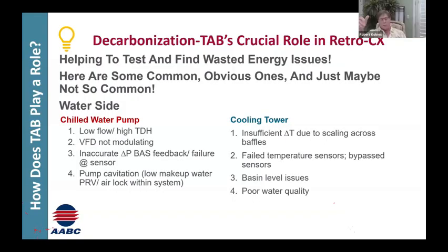I'm also on a project right now where we've got the pumps in parallel, and without that check valve in place, the two idle pumps are rotating in reverse. That's indicating that we've got backflow through them. Not a lot, but it is happening. Yep.